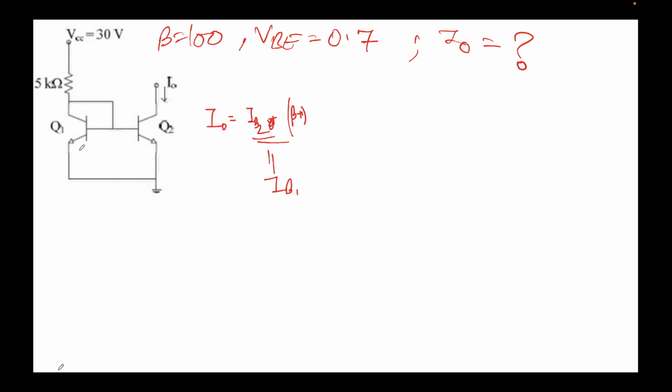How I am saying that is because these two transistors are exactly the same. The base is at the same potential for these two transistors as well as the emitter. So as long as the base and emitter are at the same potential, these transistors are equivalent as far as the current flowing through them is concerned. They may be different in other aspects, but the current flowing through them is constant. Now whatever resistor you may apply here, whether you apply 10k or 100k, it's independent.